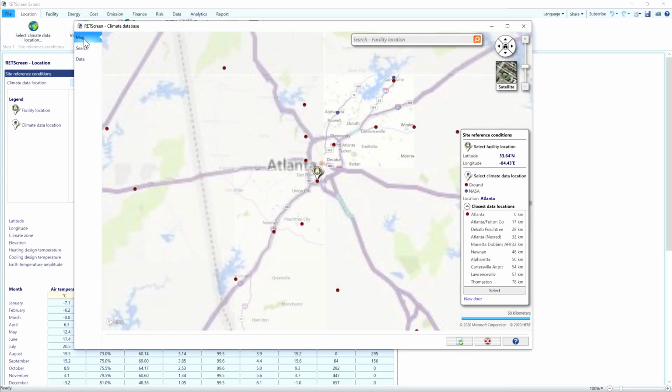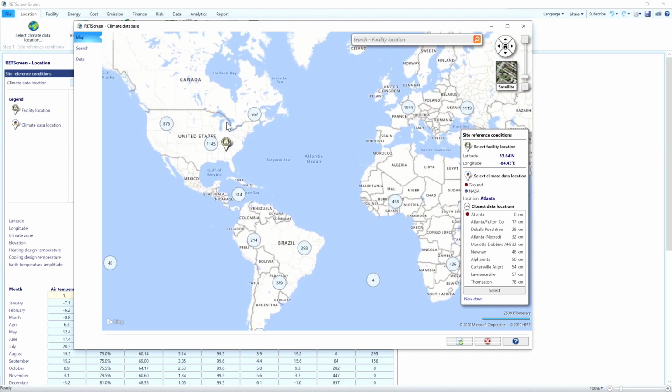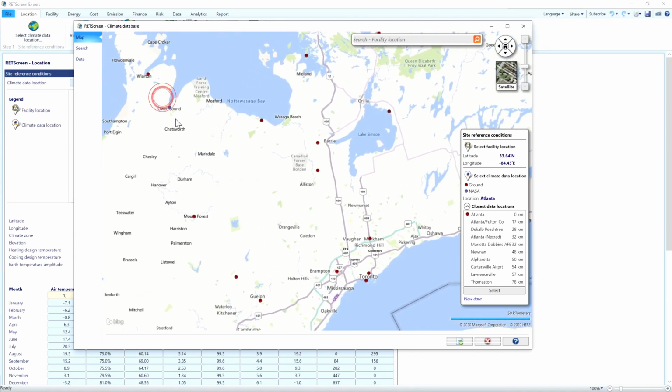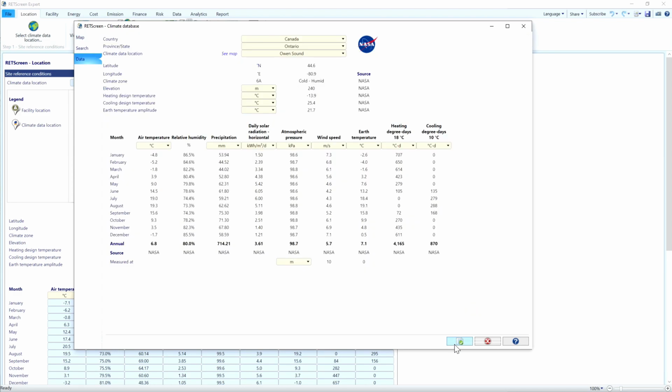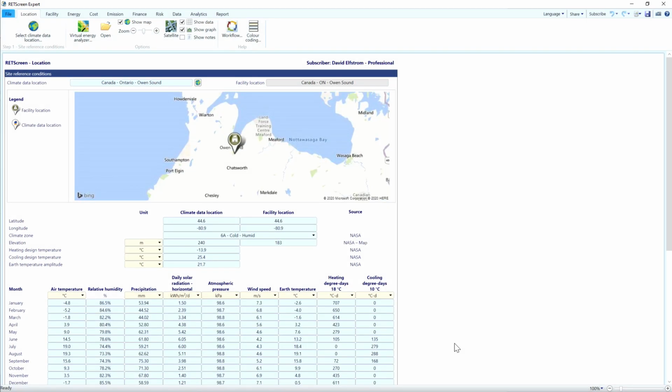Also, ground values measured at an airport can be a little different than a nearby dense urban location. In short, RETScreen ground-based climate values for design temperatures are reasonable to use, but if you're modeling an individual heating or cooling measure and the climate data shows NASA for the design temperatures, caution is warranted and you should probably consider a different source.